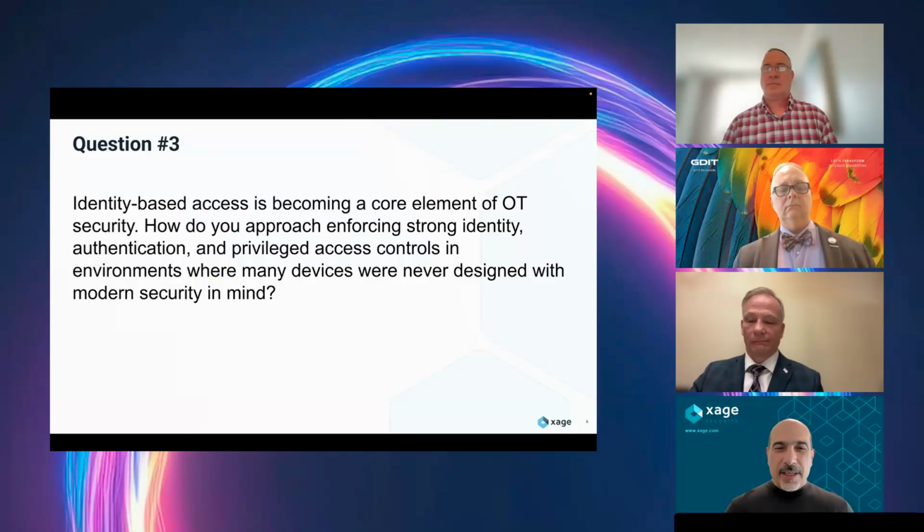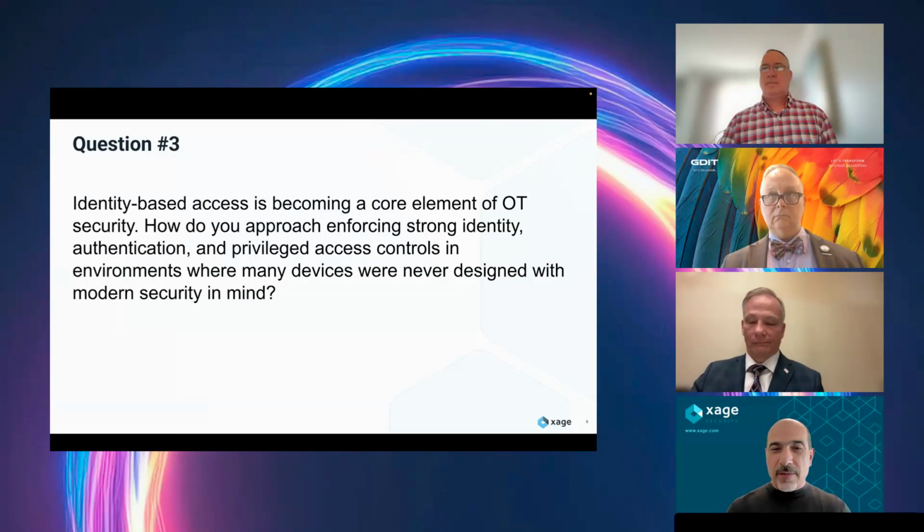So identity, authentication, and access management are really the core principles behind zero trust. And when we think about them in an operational environment, we really need to consider the assets that the operation is using. These assets are designed to be there for decades. It's not uncommon to see a PLC that's been there for 20 plus years. Fundamentally, these assets cannot be changed. You cannot just inject identity-based controls into these assets.